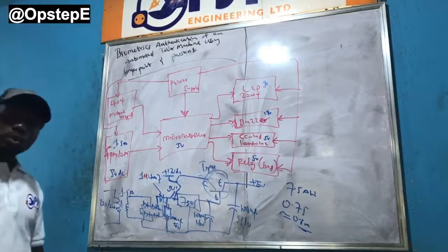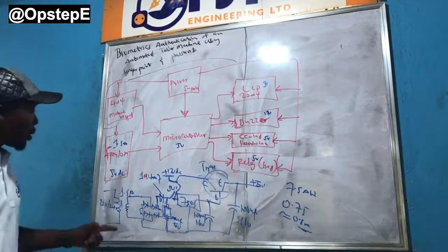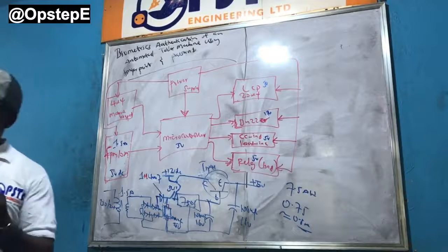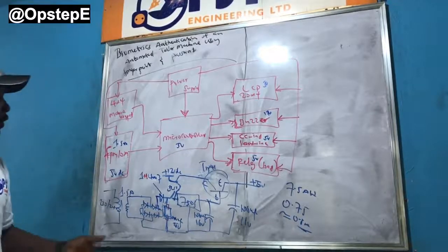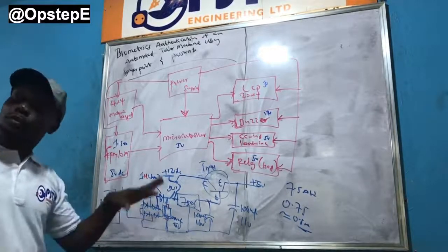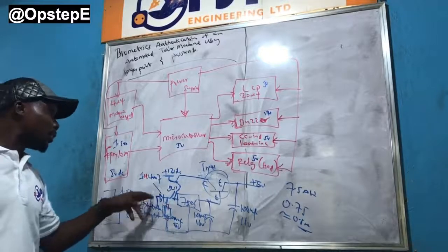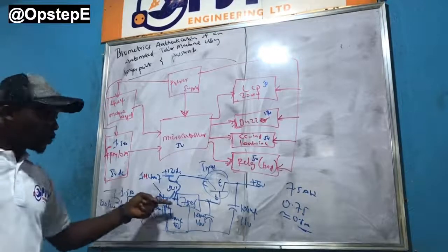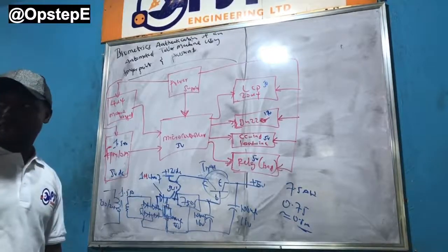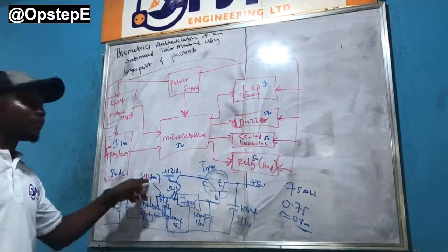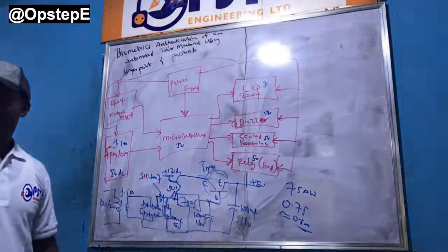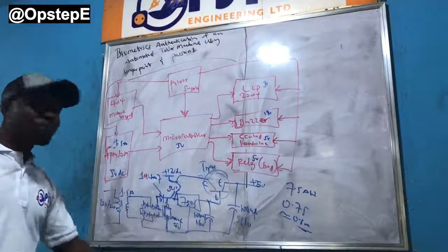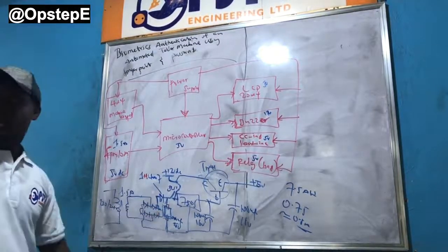Another thing you should know, please look up. Because we are using 4 diodes to create our bridge rectifier, if we are using 1N4007, don't forget that it means not more than 1 amp can be used. Not more than 1 amp will flow through it. So even if we had kept a 1N5408, it would have been a waste, because this diode itself will not allow more than 1 amp through our wires.